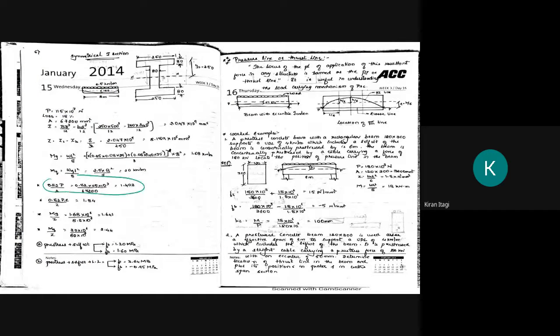Therefore the procedure is the same. Here what I have done is calculate the direct stress separately, and the bending stress separately. So just write down up to the given things. At the first condition, pre-stressing force plus self weight, the formula will be Ft equals P upon A minus P into e upon Z. Only self weight means you should take Mg upon Z. If we are asked self weight and live load, then you have to take Mq upon Z. So the first condition is pre-stressing force plus self weight. The second condition is pre-stressing force plus self weight plus live load.